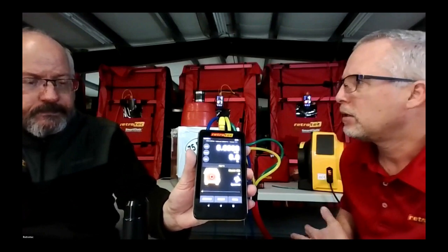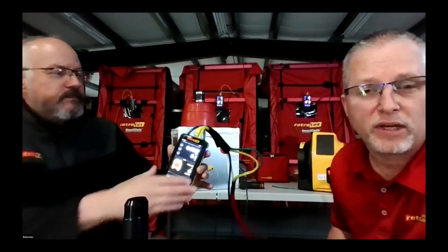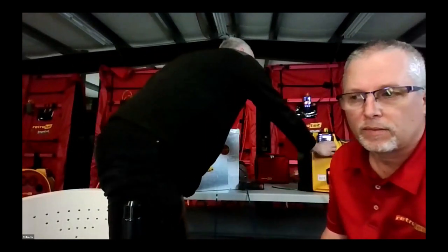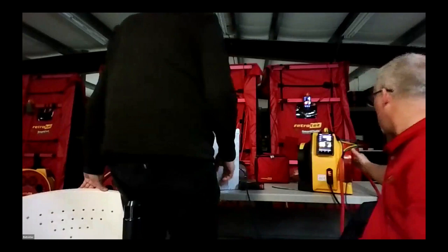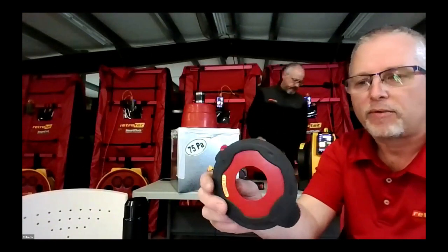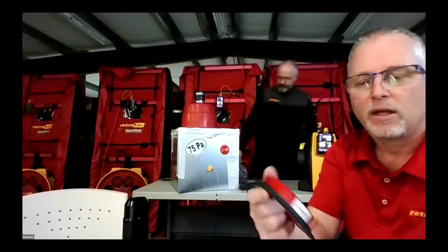It can measure down to 0.29 CFM with some additional orifice plates. With the stock ones that come with it, I believe it's down to about 2.9 CFM, so just under 3 CFM. The orifice plates are very easy to change out. They just snap in and snap out, and it comes with 5 different ones to get you there.